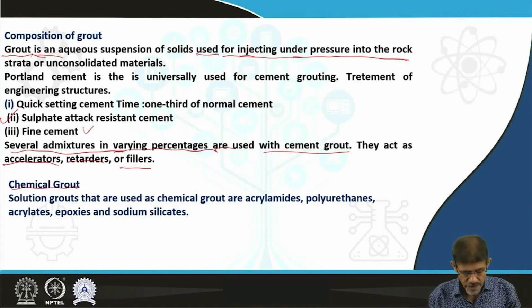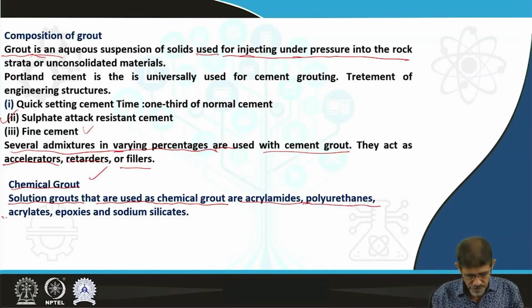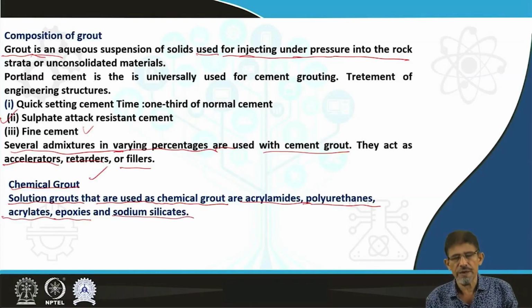Chemical grouts are very limited in use in comparison to cement grout, and chemical grouts are solution grouts. The chemicals used are acrylamide, polyurethanes, acrylates, epoxies and sodium silicates.